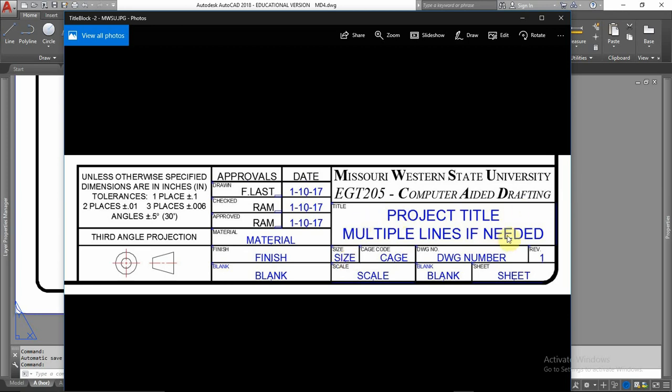This right here is a title. It is a little bit more important. So more importance, we usually give a little bit larger size. So this would normally be double the size. So if these are 1/8 inch, then this would be a 0.25. If these are a 0.12 inch, then this would be approximately a 0.24.